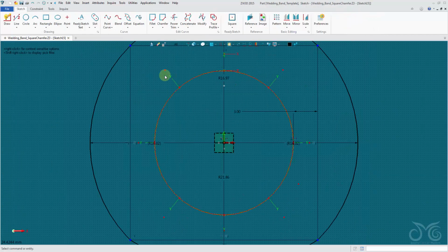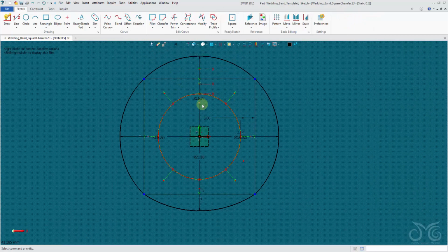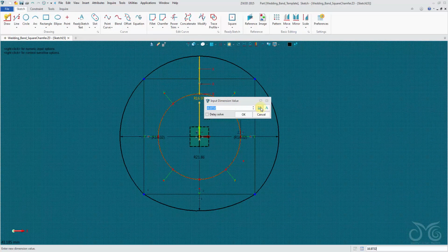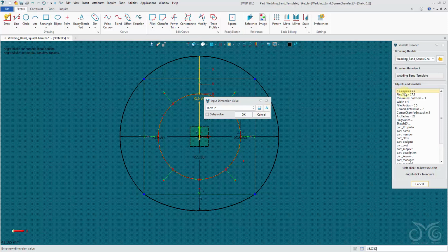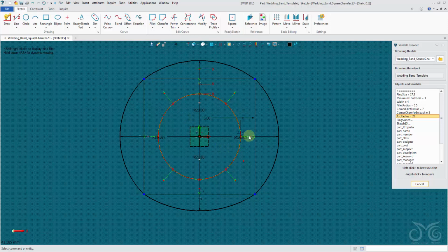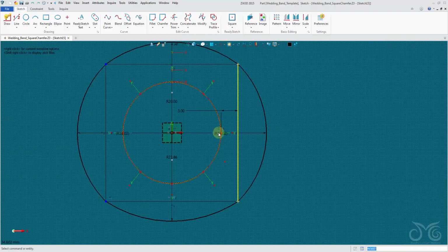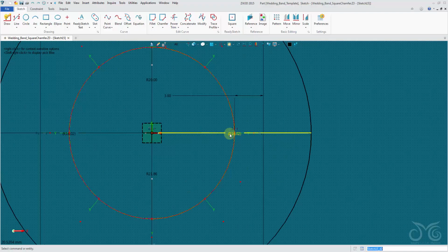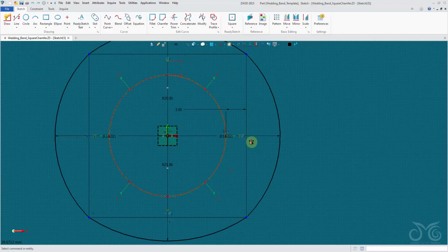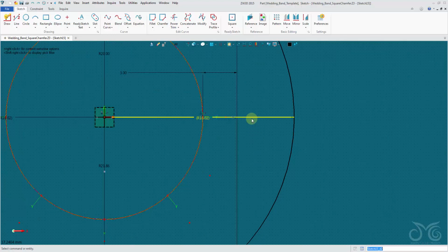You can double click on it. Okay, now we can link up this variable, arc radius. Done. Now I want all of these other radiuses to be linked up to this one here. Now these radiuses are in parentheses. This is because they're brought in with a constraint. Now if we right click on these, toggle reference, okay, it changes it to a live driving parameter.